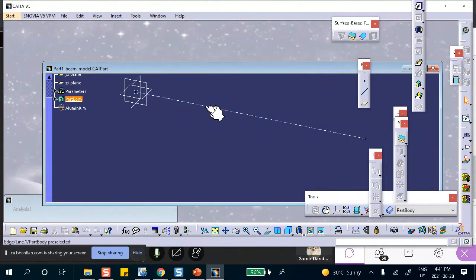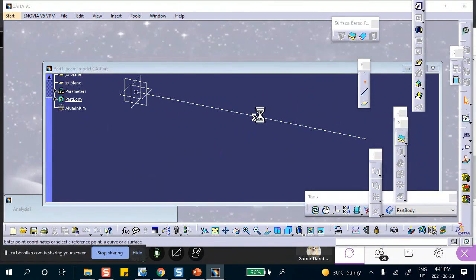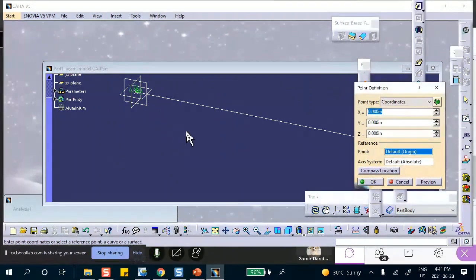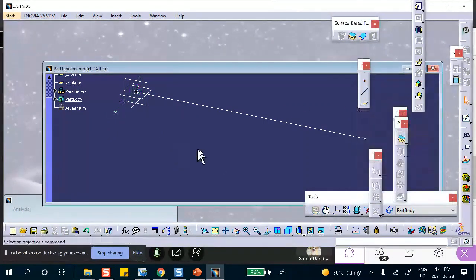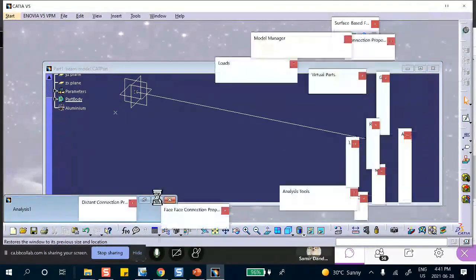If it's a circle, don't worry about it. You don't need an orientation point. But if it's not, then there are many points that I can pick. I suggested, when I was discussing these, that there is a process behind this, but I can't repeat the process every time. If you want, go and look it up. I'm going to create a point, for example, at the coordinate here, x being, I don't know, 2 inches, something like that. Totally useless, totally irrelevant, okay? But this allows me to orient the beam properly.